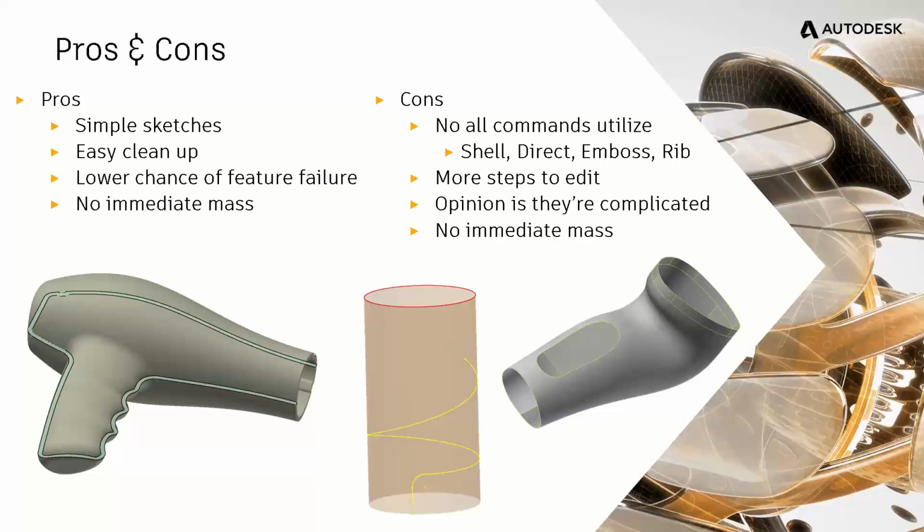Also, in a drawing view, one of the pros is surfaces don't show up by default. We have to go through a couple of clicks to get those to turn on and display. You can also set a component in an assembly to be a reference component, and it is very much seen as a surface. Its mass does not impact the assembly, and it does not automatically show up on a drawing view or a bill of material. The result in the drawing environment for a reference component and a surface component is very much the same.